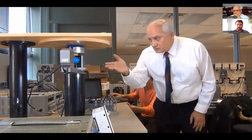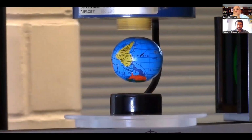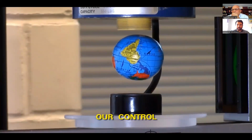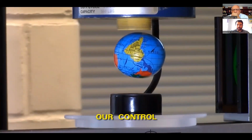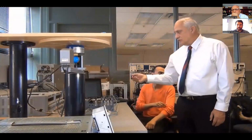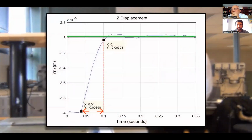We apply now a new control algorithm on the levitation system, and we're going to give some step inputs and check how the ball is reacting on the vertical plane. And as you can see, there's almost no oscillation when we go from one step to the other. If we look at the time response and zoom on it, we can see that there's almost no overshoot, no static error, and in less than 60 milliseconds, we get a nice response. Note also that the rise time and the settling time are equal.